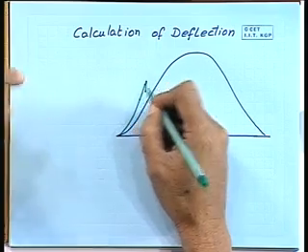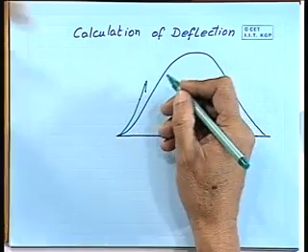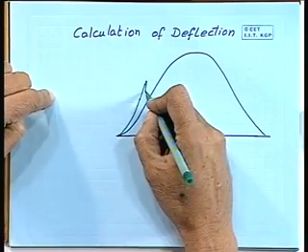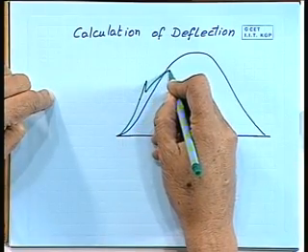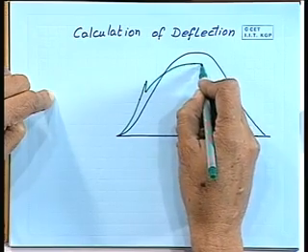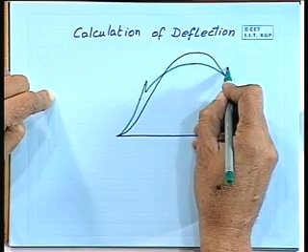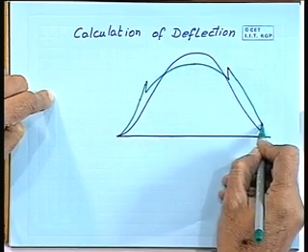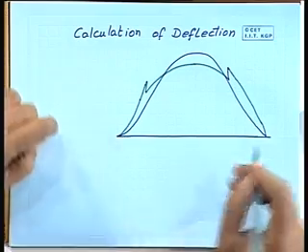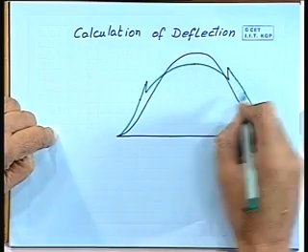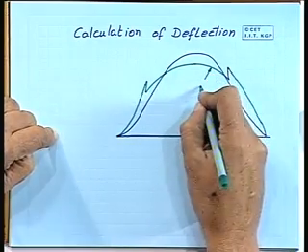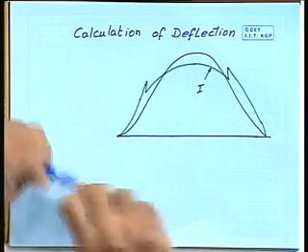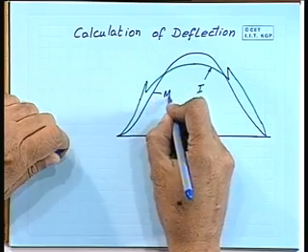that means, as I am trying to depict, suppose there is a poop, then suddenly when the poop deck is over, it comes to the main deck, and therefore there will be a drop in the midship sectional area, and then when the forecastle comes, it again goes up, and then let me continue and say that it ends up like this. Okay. So, we can say that this is the I variation along the length, whereas this is nothing but the bending moment curve.